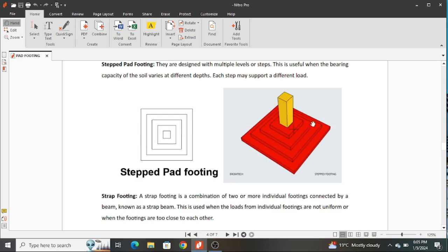And this is actually economical because assume this engineer realized that he needs a depth of 1 meter, and this depth is most critically needed at this point. So, and if we have maybe 400 millimeter at this point, it is still okay. So you can do a step footing, and it will take care of the shear at that point.